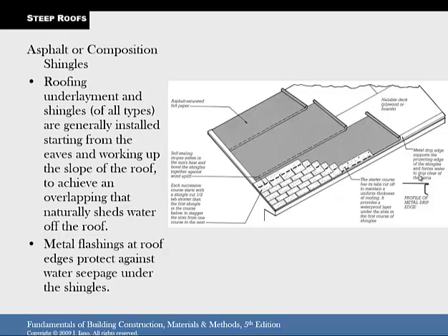We're just showing you the metal drip edge. It's still important to have that because if you don't have that drip edge, which makes the water fall away from the building, it will just run down the side of your wall and cause stains and corrosion.